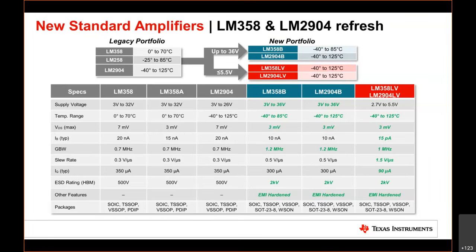Gain bandwidth has been increased. The ESD rating has been increased to 2 kV human body model. And we've integrated those EMI filters. And now we're releasing more package options than we had previously.